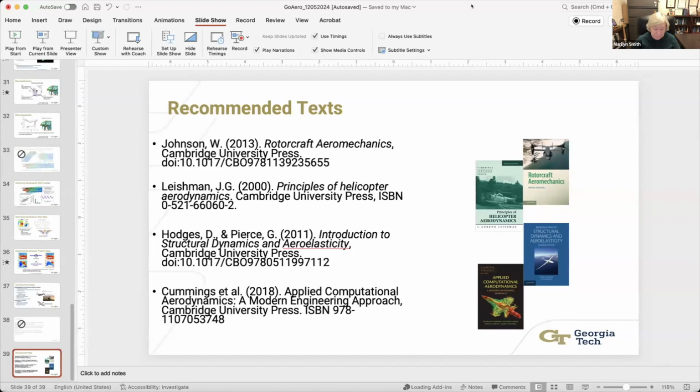What tools or methods would you suggest for determining blade count or solidity? Oh, you can do that just with blade element theory or blade element momentum theory, depending on whether your key criteria is hover, climb, or forward flight. Forward flight is blade element theory, but you can use blade element momentum theory in hover. You should be able to do your blade count with something like that. You don't need CFD for that, and solidity as well.